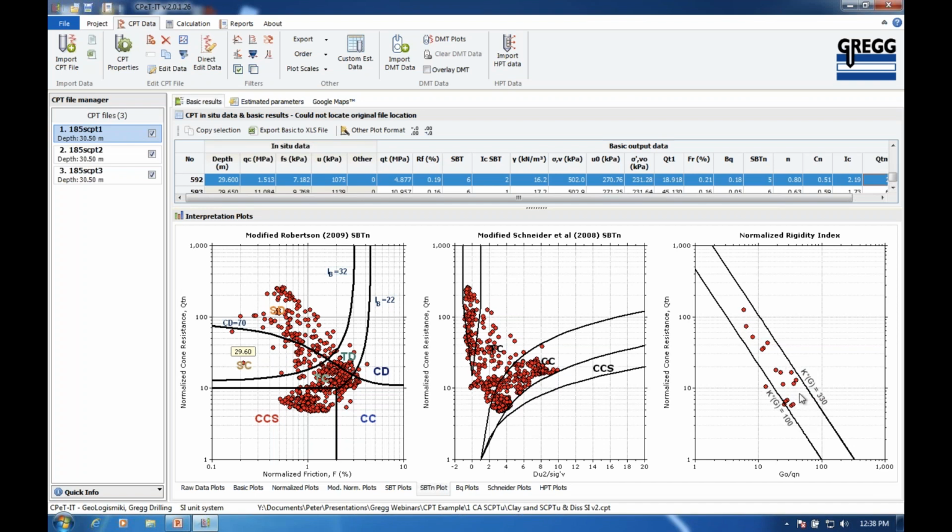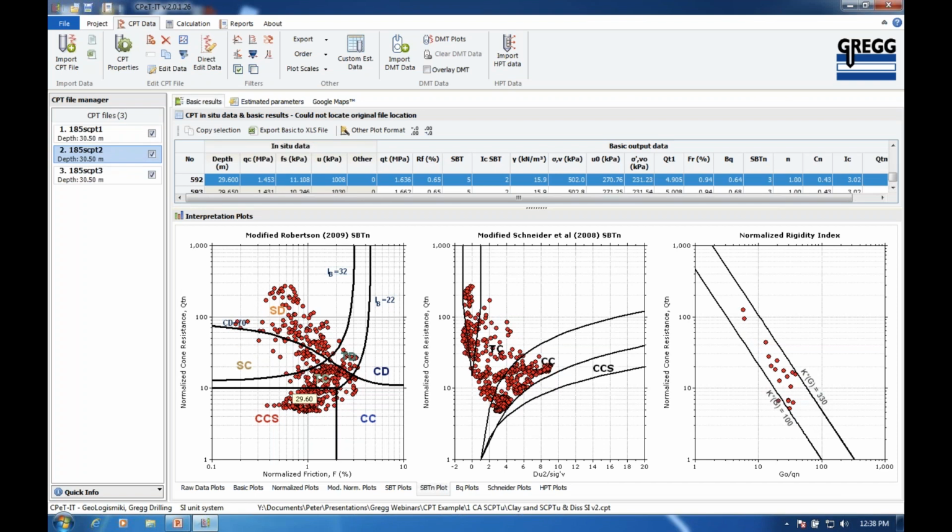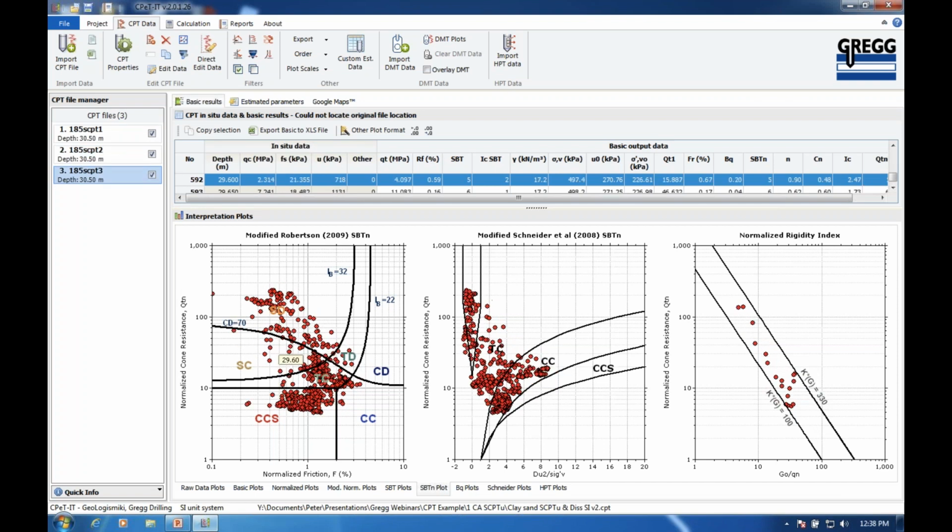So it's saying the soils at this site are relatively young and appear to be uncemented, and that's consistent with the geology of this site, that we are in fact expecting a sort of a Holocene age deposit here, which is relatively soft. It's mostly clay with some interbedded sand layers, and sure enough, all the shear wave velocity data combined with the CPT is falling within that band. In fact, if I quickly flip through all three of them fall within that band very nicely.